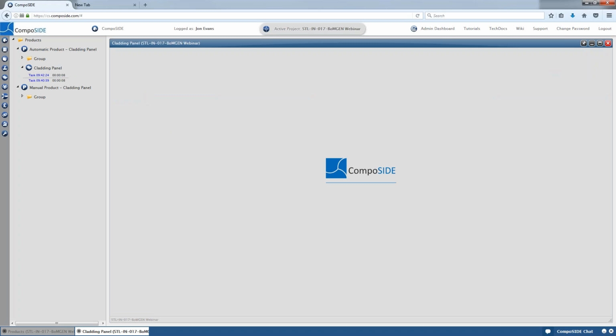So I've created this landing panel within FE space. I brought it in from a step file, applied a laminate to it, defined a load case, a basic pressure load case, and run the analysis. I've optimized my laminates, and I'm happy with the results that I've got.